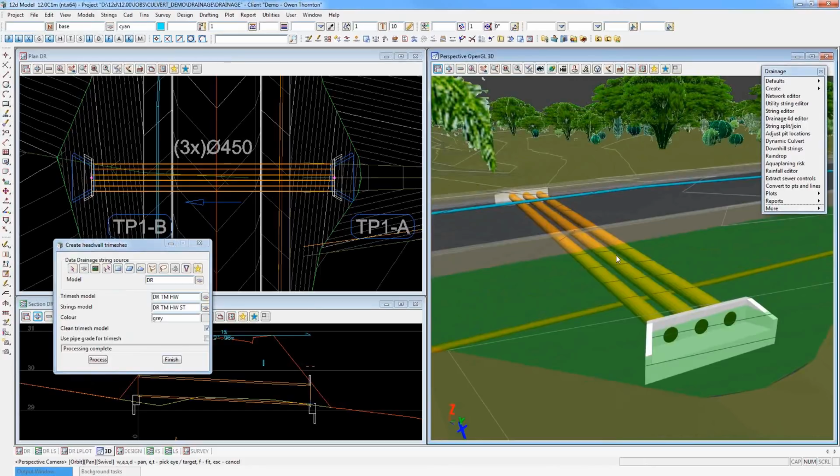This macro was developed from a particular job, and they had some hardwired head walls that they needed to model. And so it's all programmed in for those. However, you can customize it at this point, and it requires editing your drainage.4d file. And so I'll just show that briefly.